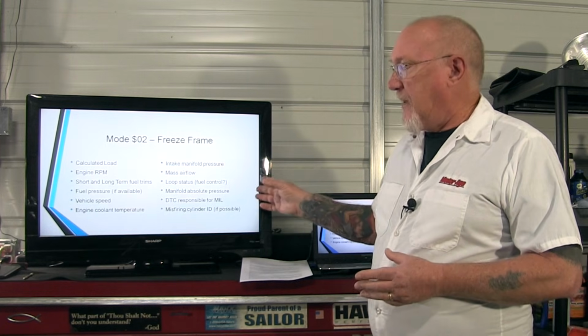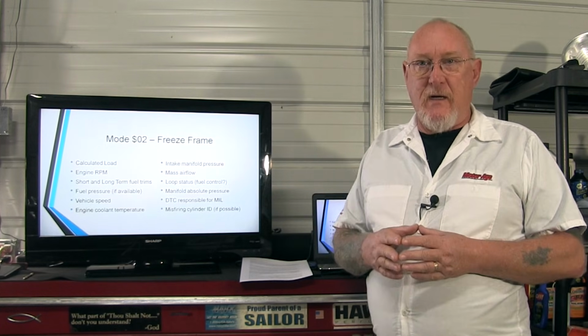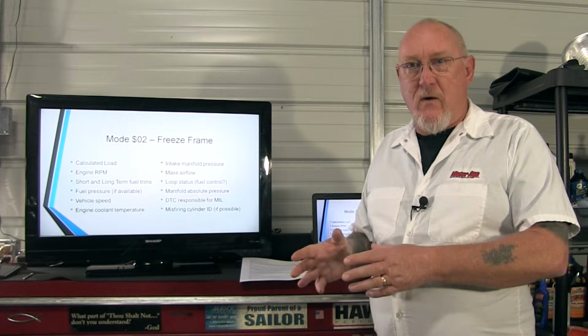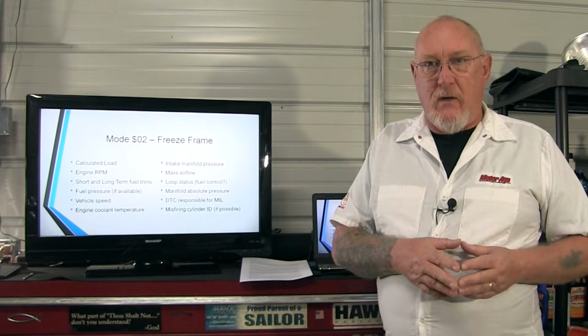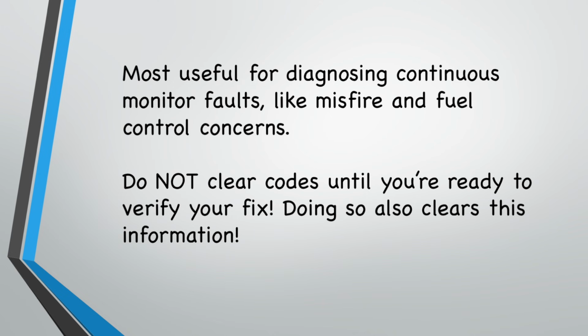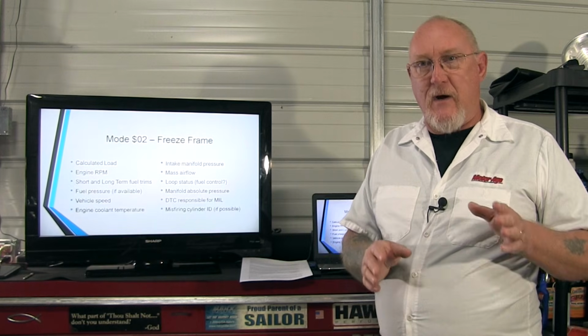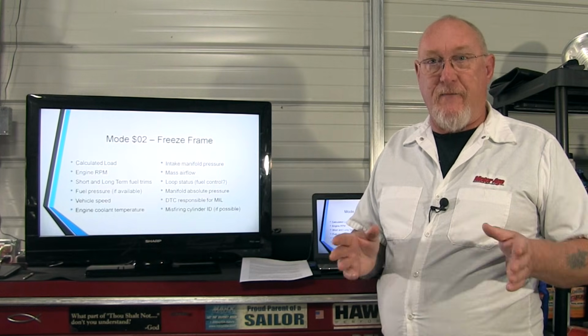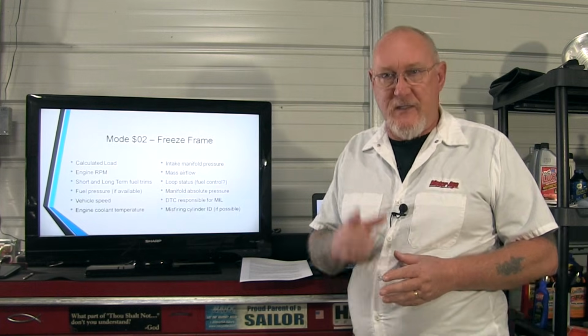The other thing I want to point out is I see way too many techs go and check the code and they automatically clear the code. Well, don't do that, because once you clear the code, you're going to wipe all that information out, and you may need that to help you fix that car. Don't clear anything until you're actually ready to test drive the car and verify the repair that you made. Let's move on.